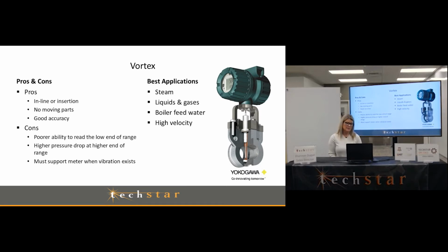It does have a little bit higher pressure drop at the higher end of the range. That's because you're shoving more fluid over something that's in the line. And then you do have to support this meter if there's vibration. And if there is a lot of vibration, then we might look at some other technologies that would be available as well, so you don't have to do that.